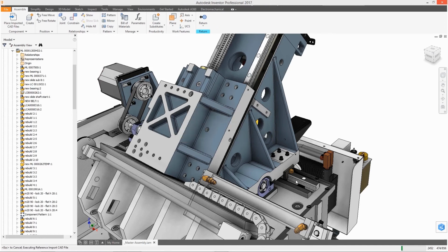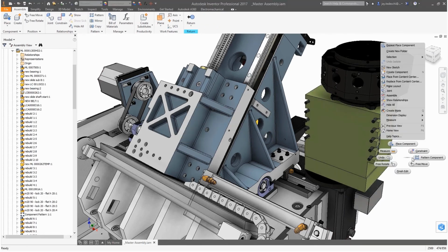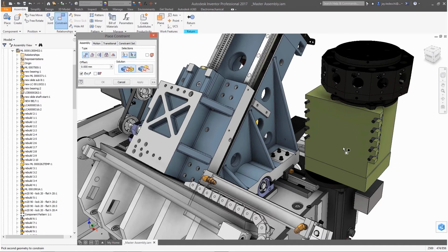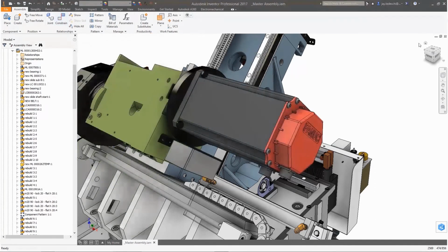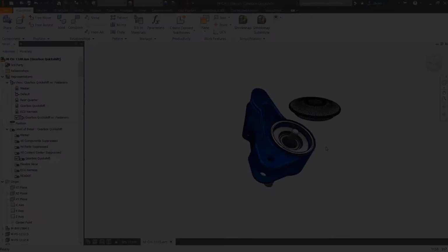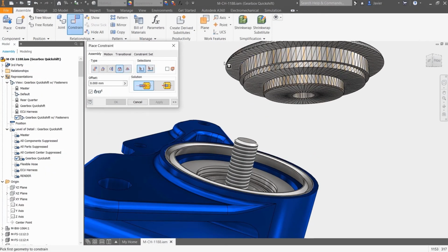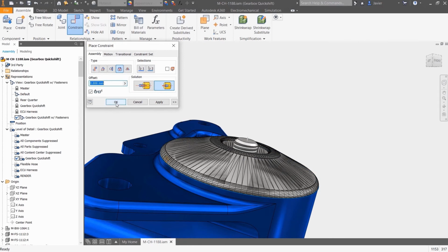If we're in Inventor 2017.4, here we can open up an Inventor 2018 file and place it inside of our 2017 assembly. The nice thing here is it has an AnyCAD reference, just like it was done, and then once you move to 2018, then it just becomes a natural 2018 file.